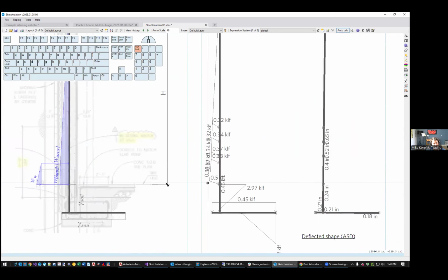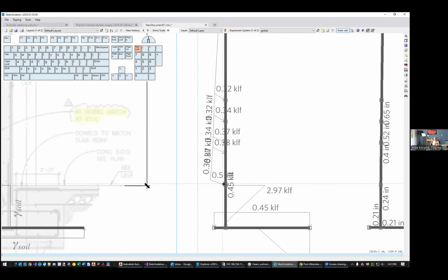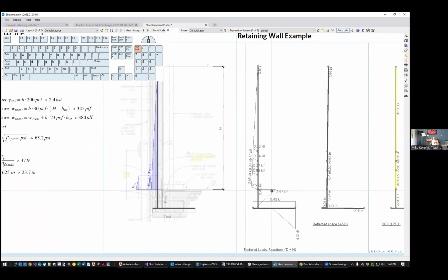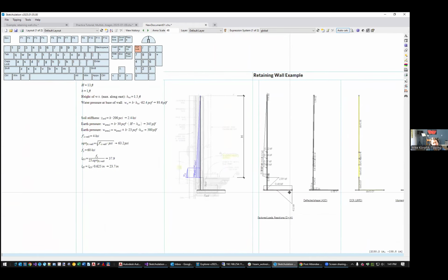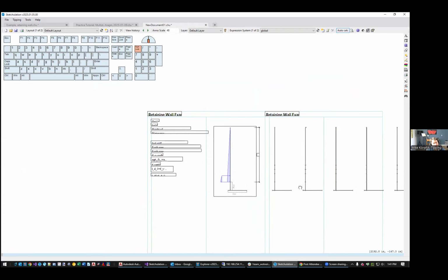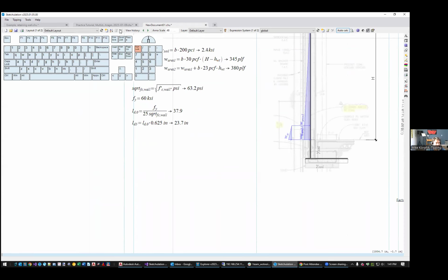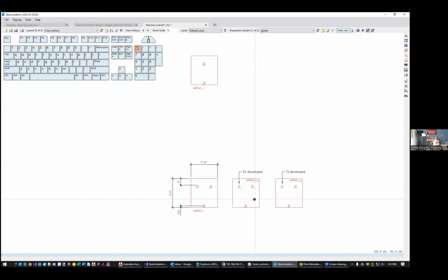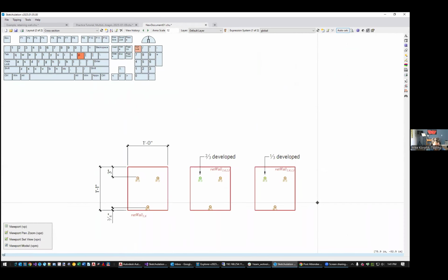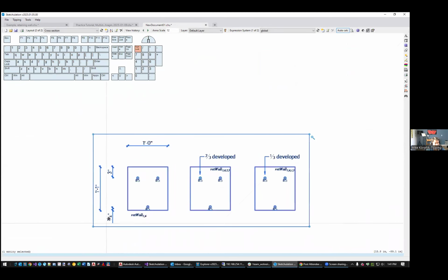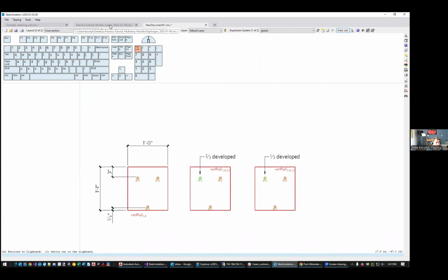Interesting thing you'll notice is that the loading is taking into account self weight, so that there's actually a vertical component of the load that slightly helps the concrete cross section in this analysis. If this were for production, I might make some viewports for my cross section. So just demonstrate that really quickly. Make a viewport here, like that. And again, this is at a scale of 12.